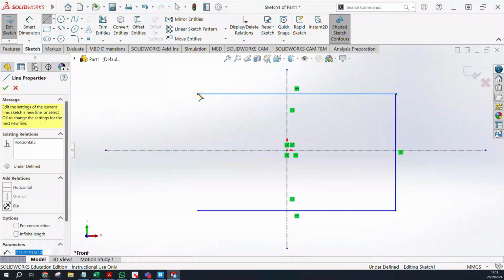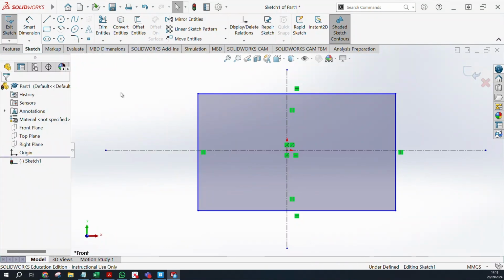So let's click here, and then you want to join them like this. So here it is a complete box. I press ESC or the escape button on the keyboard so that I come out of the line command. If you see this one is in gray or dark color, it means that your sketch is complete. Complete means all the lines are connected with each other and it is solid now. It's not open-ended, it is filled now, so you can do the extrusion.